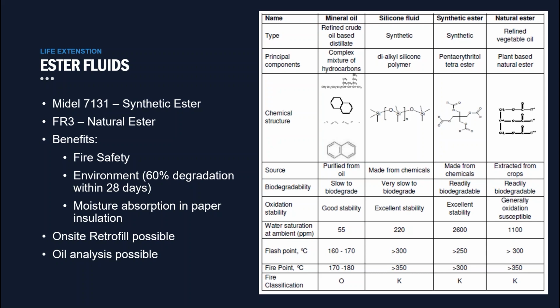We can retrofill a transformer on site, certainly above 66 kV. We recommend you work with the manufacturer of the transformer and perform an engineering assessment, so we can help with this. And after the retrofill has been done, we test the fluid in a very similar way. We take samples of the fluid, we test them in the lab. And one of the tests that we recommend after the retrofill has been completed is fire point, just to check that the procedure has been done successfully.